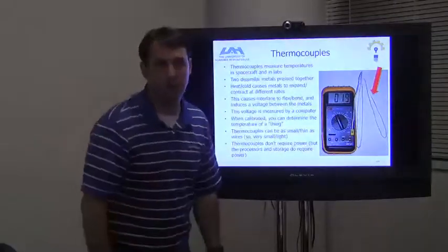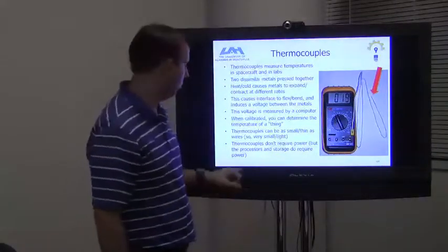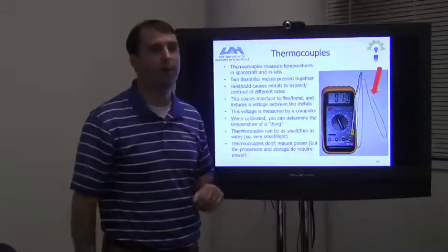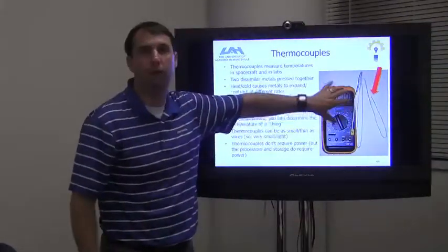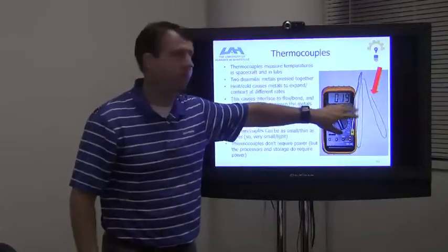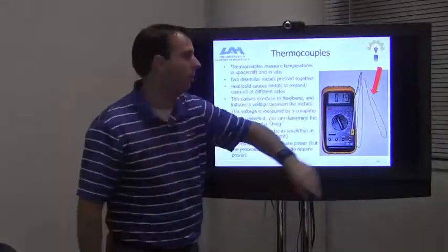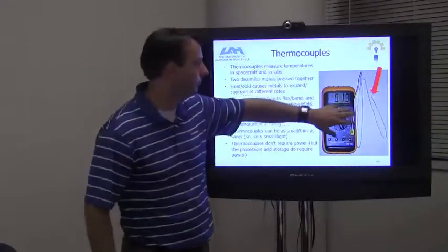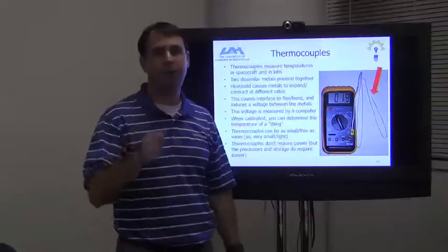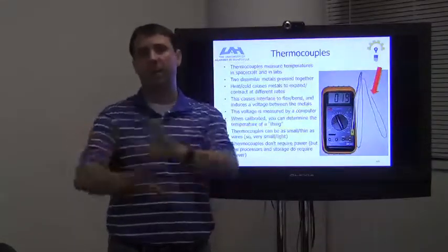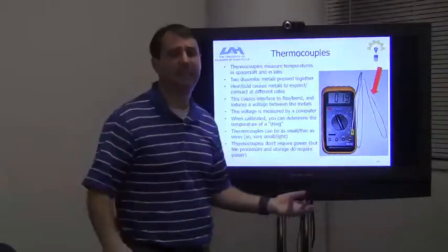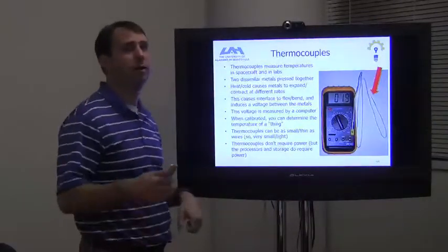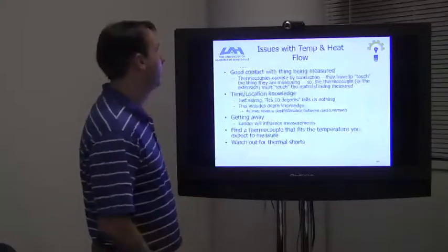Thermocouples are extremely robust. Basically, it's just 2 wires. They don't require power, really. They actually create a little bit of power, but they don't require power to operate. The computer itself requires power. Whatever is reading the measurement requires power, but the thermocouple itself does not, which is a bonus. Pressure transducers operate very similarly also. So very robust. We put thermocouples on everything, on the outsides of planes even. It's basically 2 wires, very light and robust, an awesome instrument.